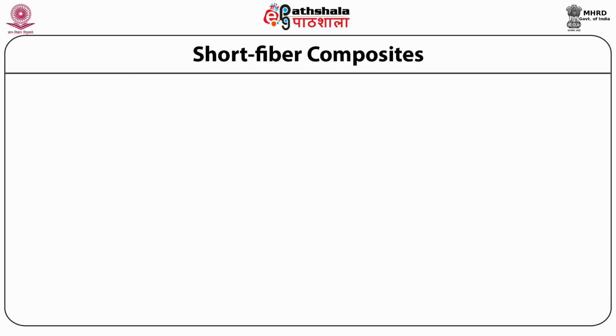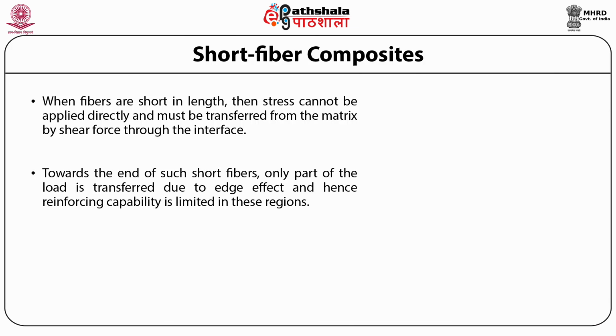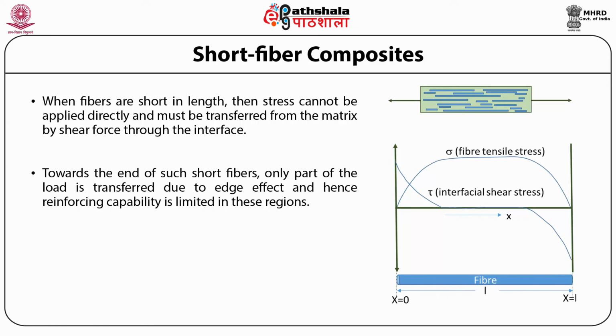Now let us discuss the elastic properties of short fiber composites. When fibers are short in length as shown in this figure, then the mechanics of load transfer changes. Stress cannot be applied directly to the fibers and must be transferred by shear force through the interface. This also implies that a good bonding must exist between the fibers and the matrix.